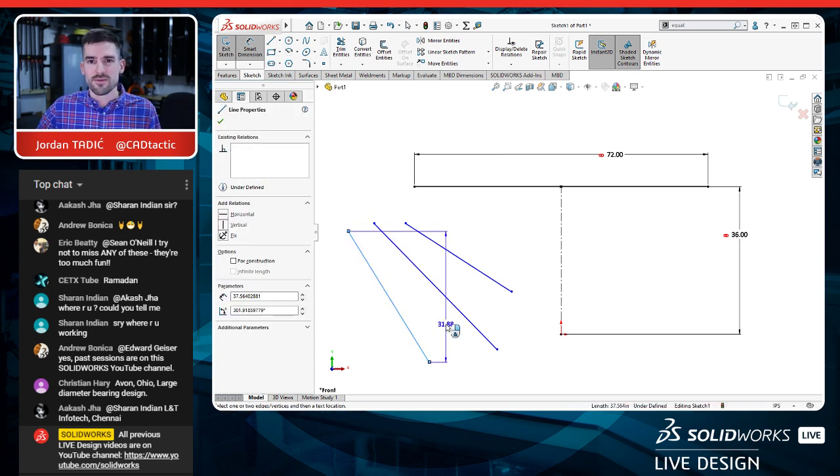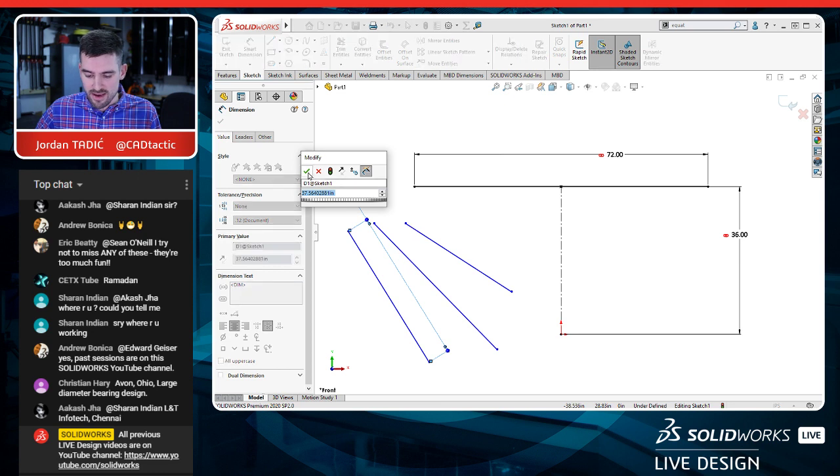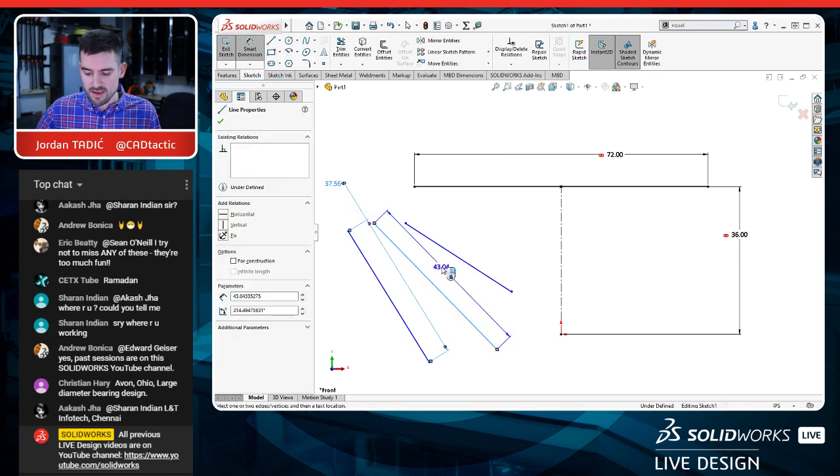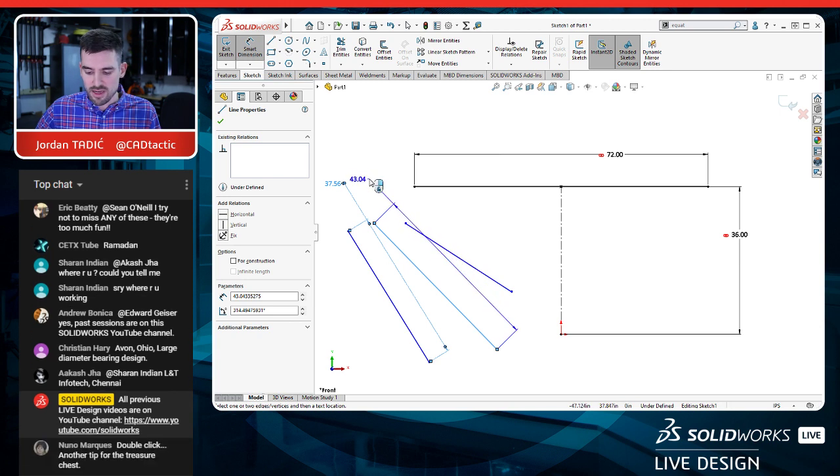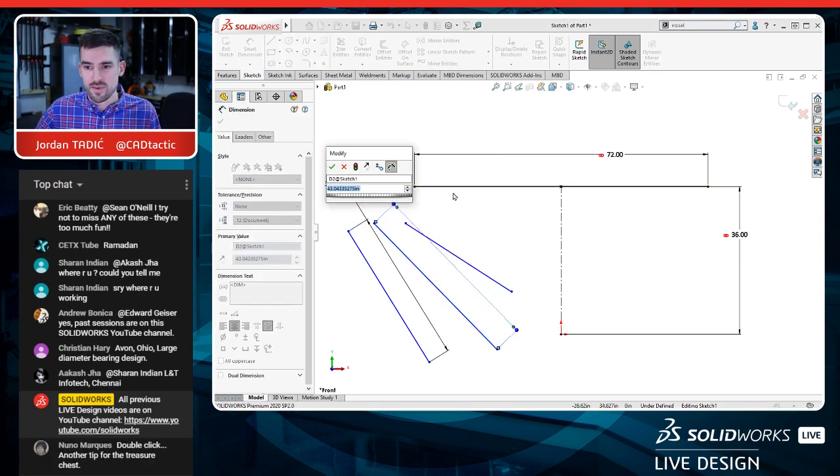Has this ever happened to you? This is so annoying. When you're trying to add this angular dimension, but you want to put the dimension up here, it switches to the horizontal or vertical length. Anyone know the trick? Always pay attention to your little mouse icon right next to the mouse pointer. It's telling me that if I right click, it will lock that orientation. So let me right click, and now I can place this dimension text wherever I want with a left click. So again, that is a left click, then a right click, and then place a dimension, and left click again. Sweet.